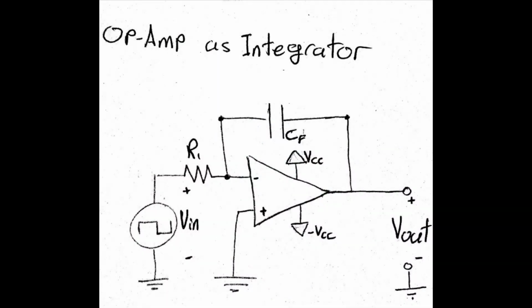At the first look at this circuit diagram, the first thing that may come to our mind is differential amplifiers. But here, instead of a feedback resistor, we have a capacitor, and it's behind the integration functionality of the circuit. So to have a better understanding, let's have a closer look.